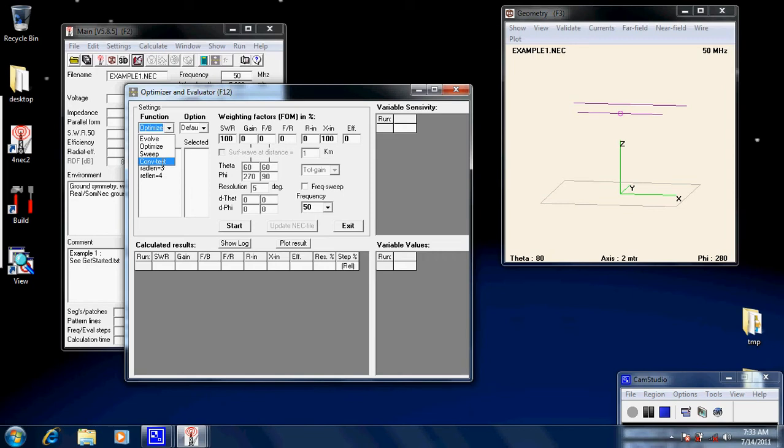It changes the number of segments and a few other factors if necessary, and it basically says, okay, if I change all these things, will the gain and the other parameters which the program produces converge to a point? Now the point of that is basically, is the antenna a stable design? So that's the reason. You probably won't use that very often. I don't use it, but anyway, it's there if you do need it. So basically it's to test the fragility or stability of your antenna design.